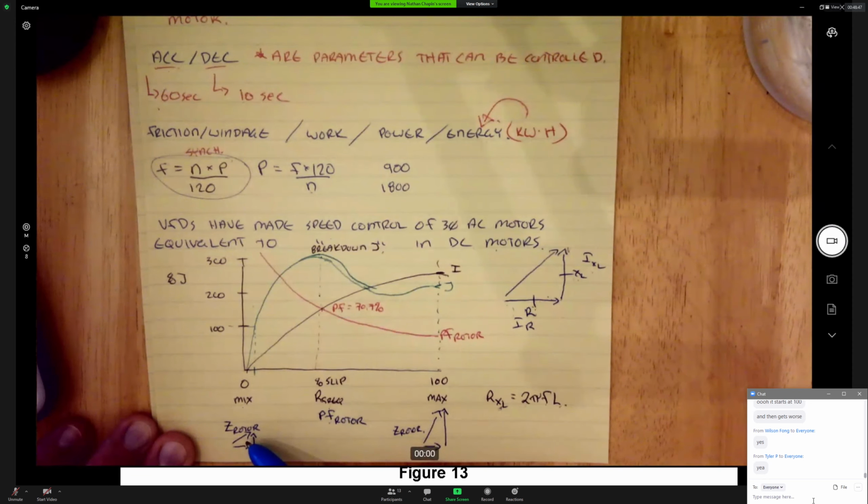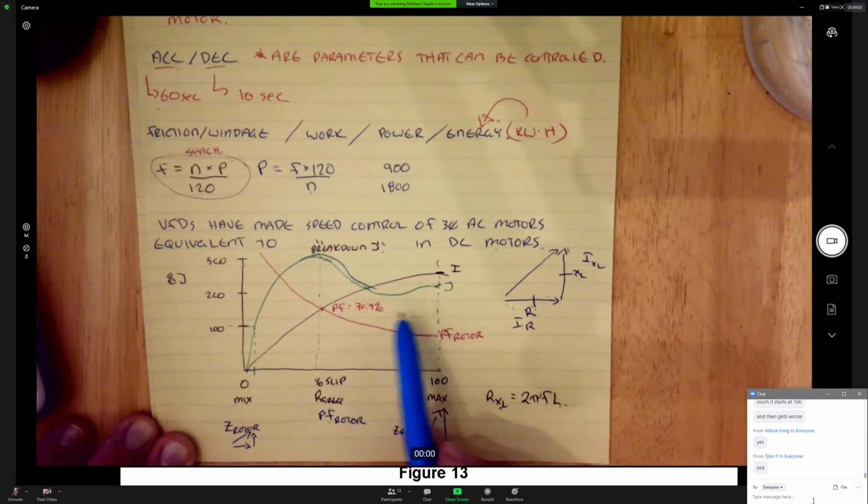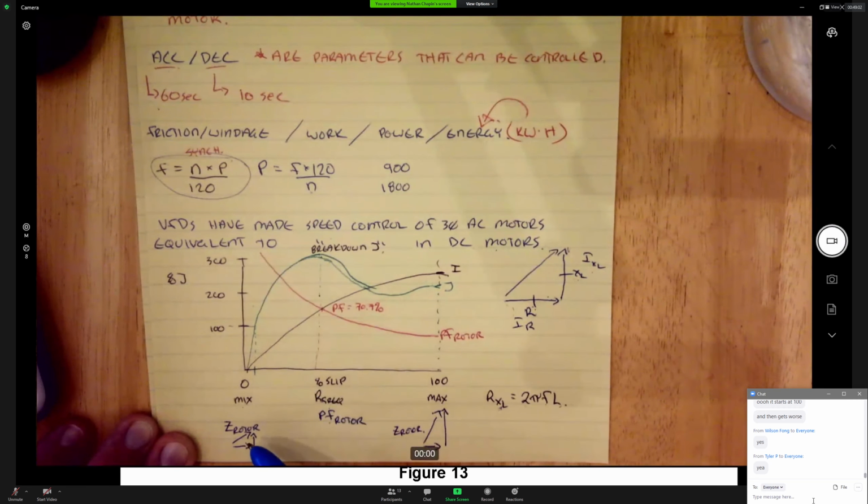So let's say this is a 600 volt motor and we're running it at a low speed on purpose and reducing this without having everything else involved with running it at full speed. So it's not cooling enough. And it should make sense that if our rotor voltage is at a maximum and our rotor frequency is at a minimum, that's going to give us a rotor current that is going to fry the motor.